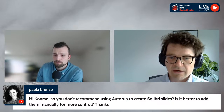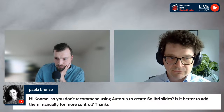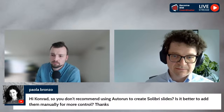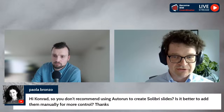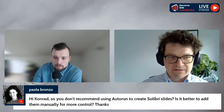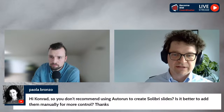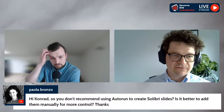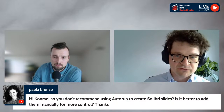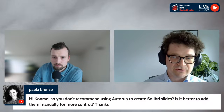I mean, on the contrary, I recommend Autorun very much. And this gatekeeper rule I've shown you, I have implemented in Autorun. So Solibri creates slides for me, but then I go through them and delete or mark as irrelevant. I sort out which are irrelevant, which are correct, and so on. So I mix both methods. You cannot automate everything. Autorun is great, but it can give you whatever results. It usually gave me like 1,000 errors, and after filtering, I narrowed it down to like 200 that mattered, for example. So you cannot brainlessly rely on Autorun.